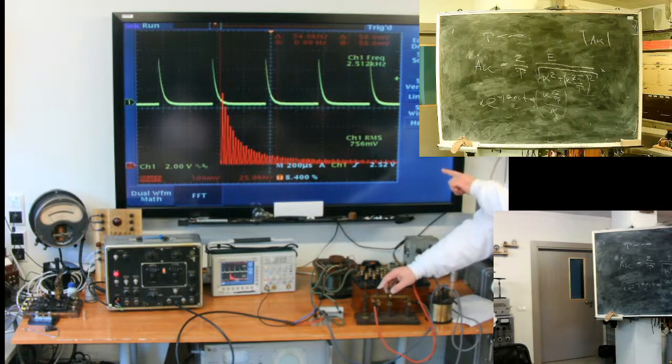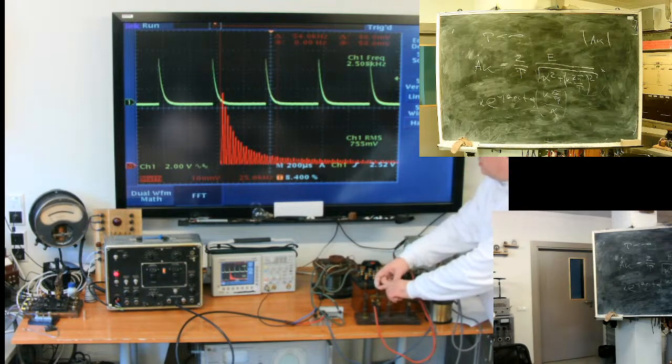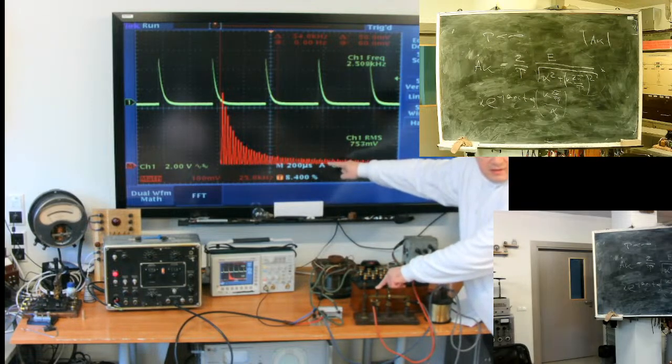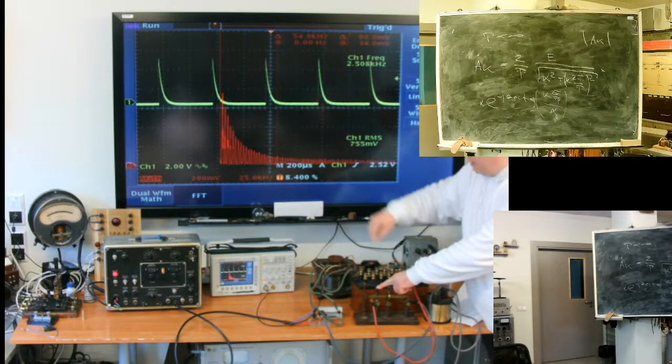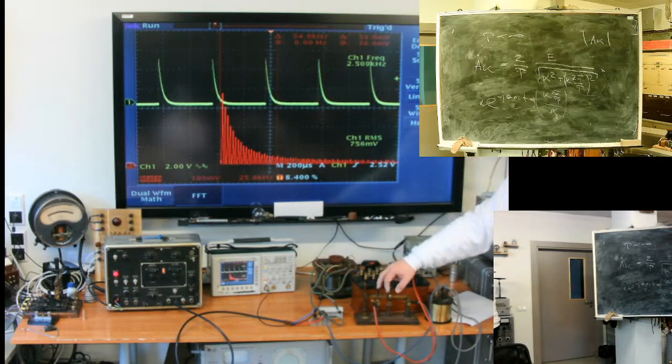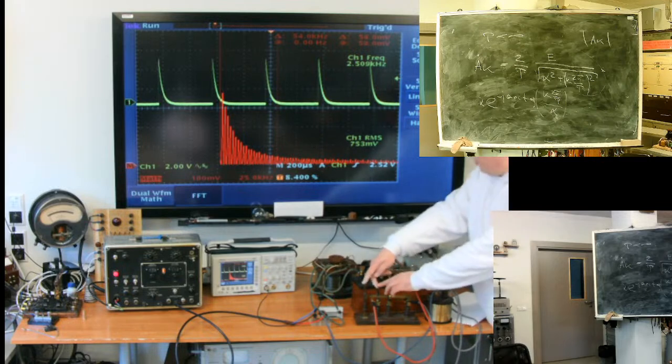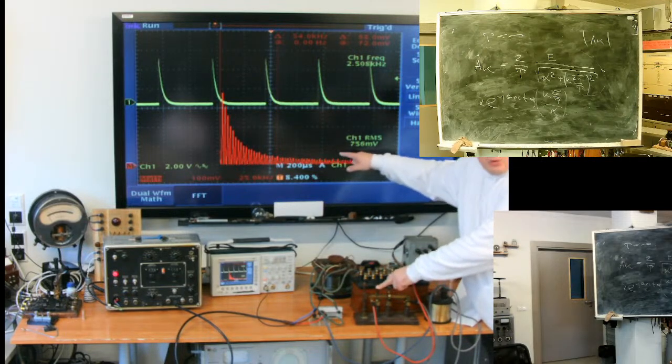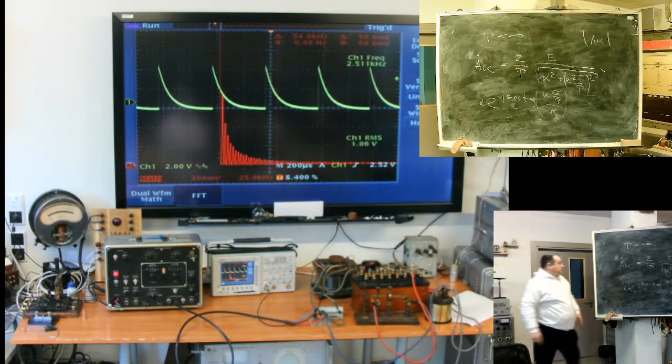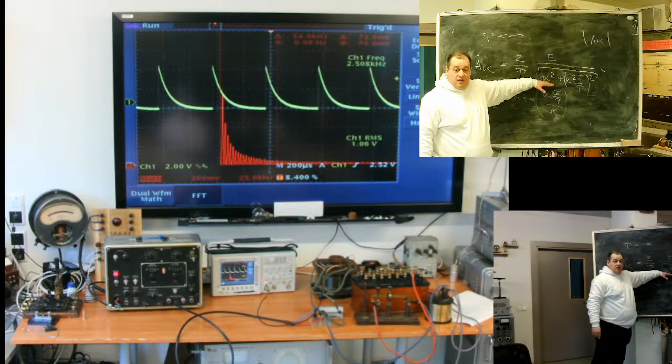You see, lines are closer, and see the tails. See what happens with the signal tail. The faster the change, the longer is the observable tail of harmonics. Because we have the case of alpha.